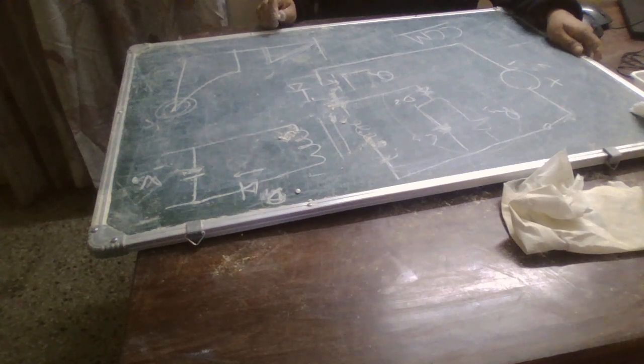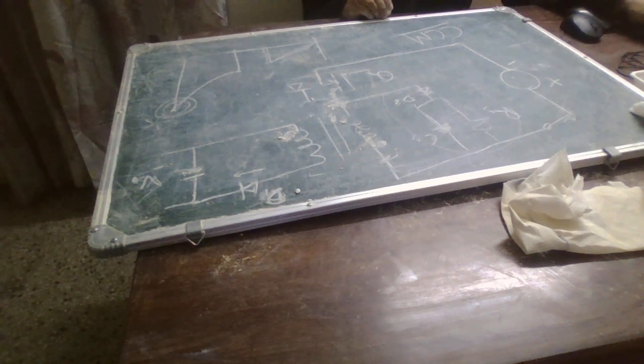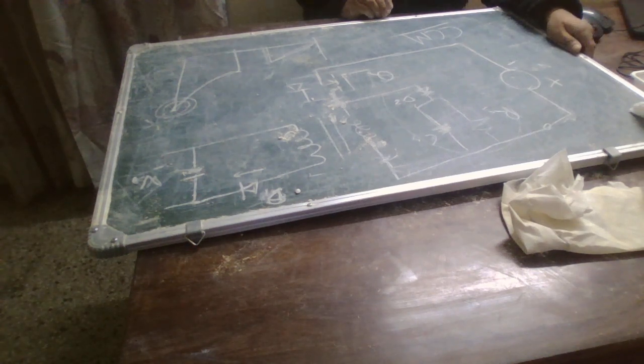Okay, the load increases the loss inside the transformer. If we take some particular output load, the load is going to increase the transformer losses, and the output diode losses also would get increased. We have to maintain a constant output voltage, therefore we can vary the duty cycle to maintain it at a constant input DC voltage.